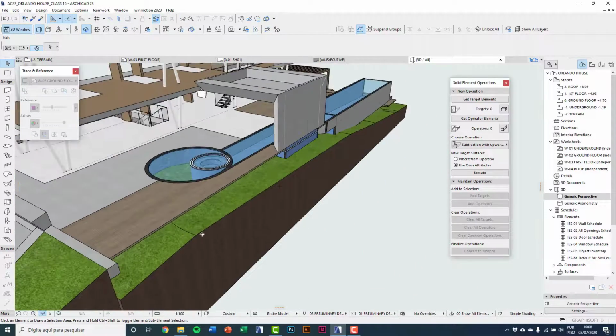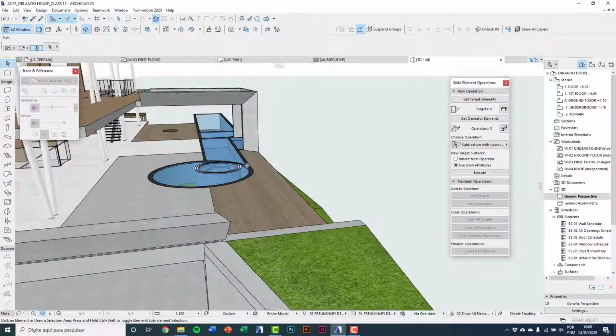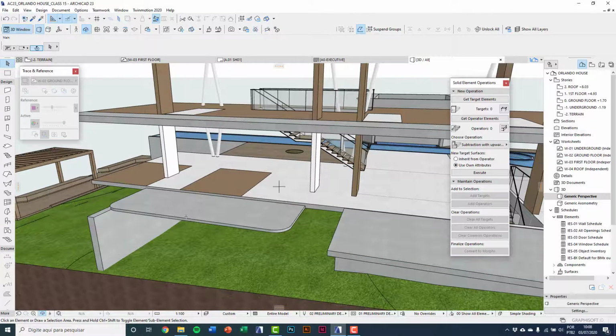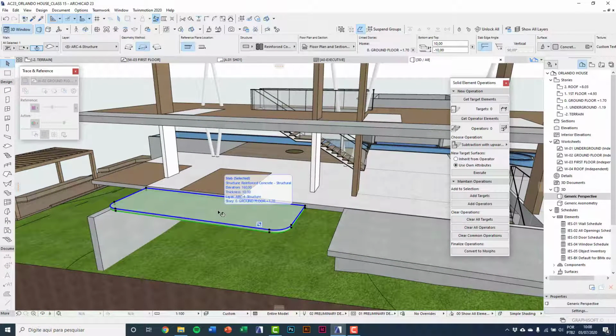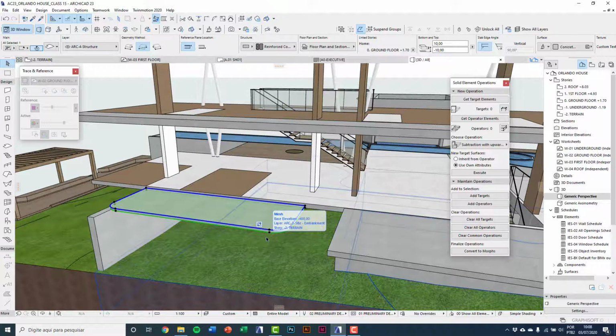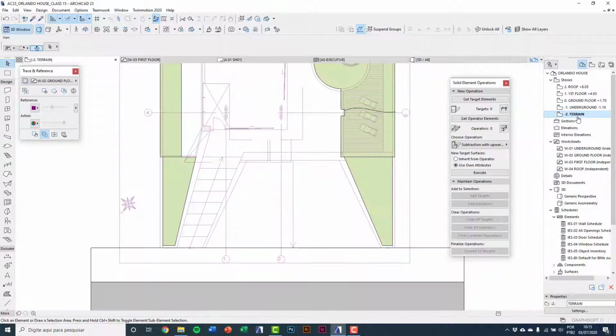Now we're going to do this grassed plain area, and to do it, we'll elevate our points to the same level. So, come here to this outer surface area, selecting the concrete slab. I see the level to home story is -10, and to project 0 is 160. Therefore, I will elevate all mesh points to 160 level. Go to terrain. I can even turn off the reference to see it better.